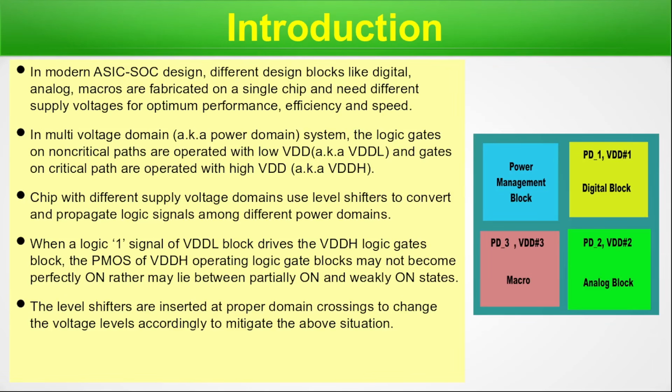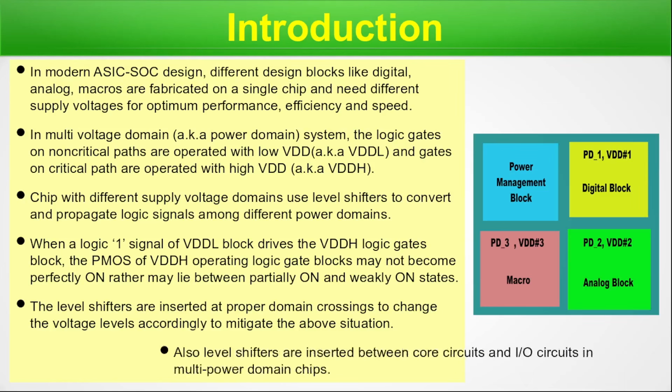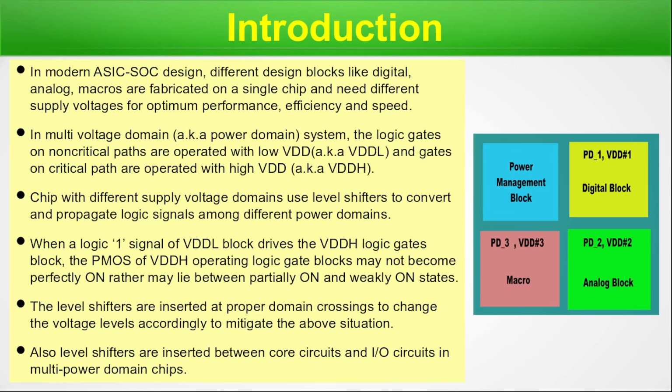The level shifters are inserted at proper domain crossings to change the voltage levels accordingly to mitigate the above situation. That means somewhere it is partially on or weakly on. So that should not happen. That is protected by inserting level shifter. Also, level shifters are inserted between core circuits and I/O circuits in the multi-power domain chip.